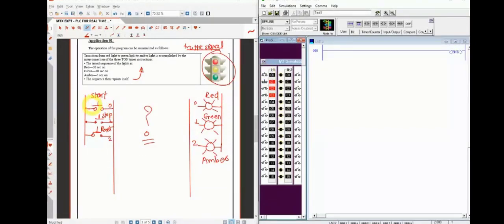I'm using this 00 as a start switch, so it is normally open. What we have to do is just right click on the symbols to change. Okay, so I want all these three normally open push buttons. Fine. Then I will start with the first rung. I'm writing that rung not for the coil to energize the LEDs, but I'm using an internal relay coil, that is a binary bit. See here how to use.